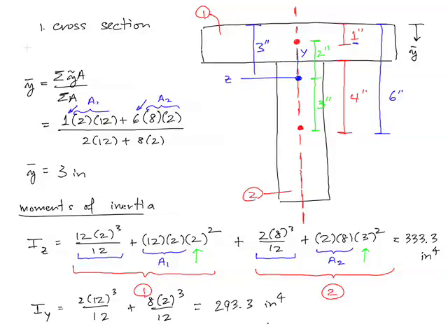Okay, so you can see that what was B up here, let me just sort of mark that, what was B up here is now H here. What was H up here is now B here. So it's sort of like we turned the T on its side and looked at the B's and H's in that context. All right, nonetheless, what we found is IZ and IY.